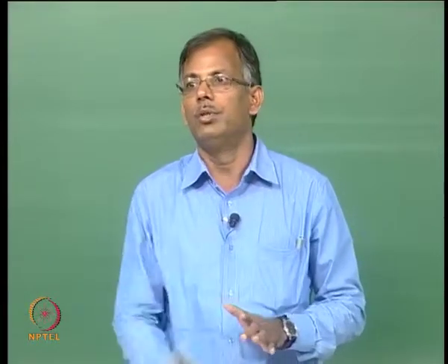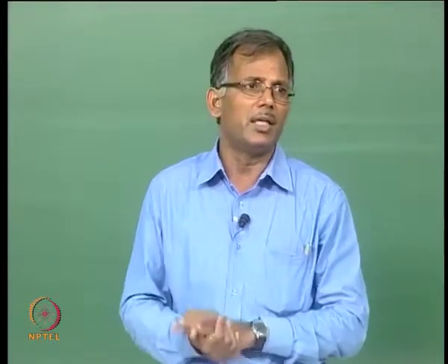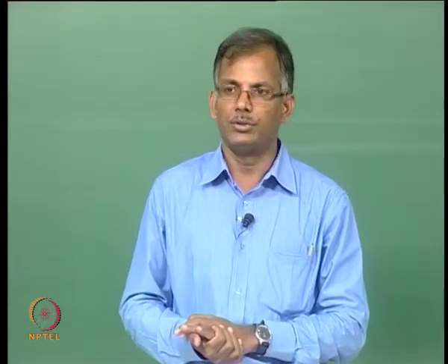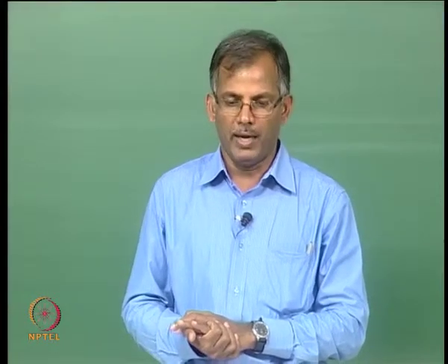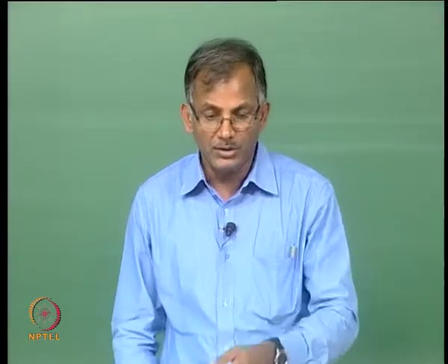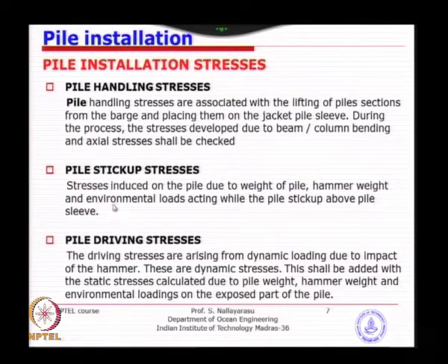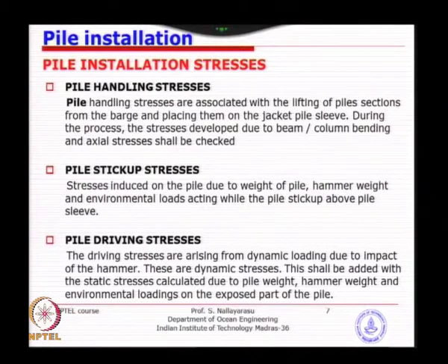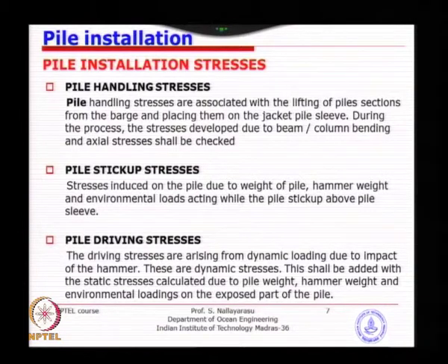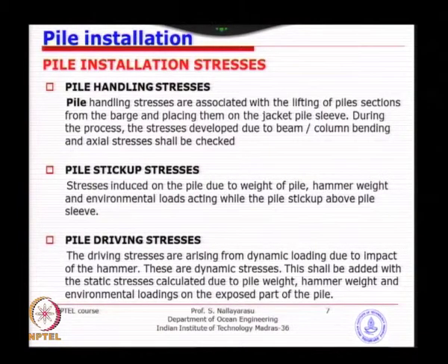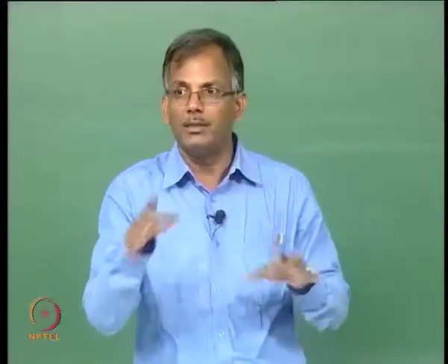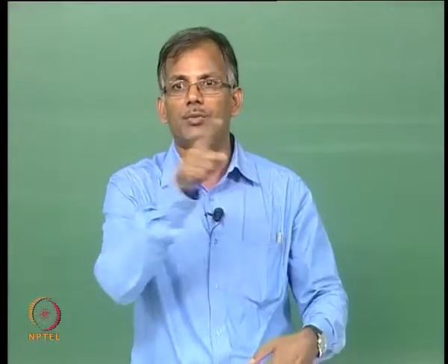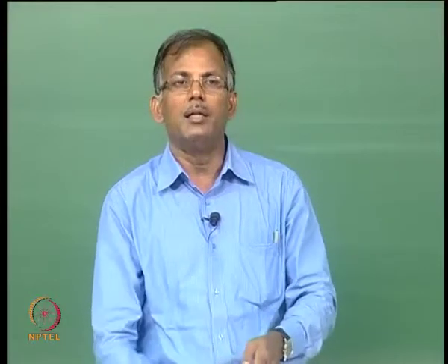that travels through the length of the pile, which we are going to see the theoretical side of this pile driving later on, but those stresses could be considerably larger than if you just take the weight of the hammer and divide it by the area, you will get a smaller stress, because that impact will cause a larger amount of stress, and the stress will not be uniform throughout the length of the pile. It all depends on what is the type of material, and stress wave travels downwards and then reflects backwards.